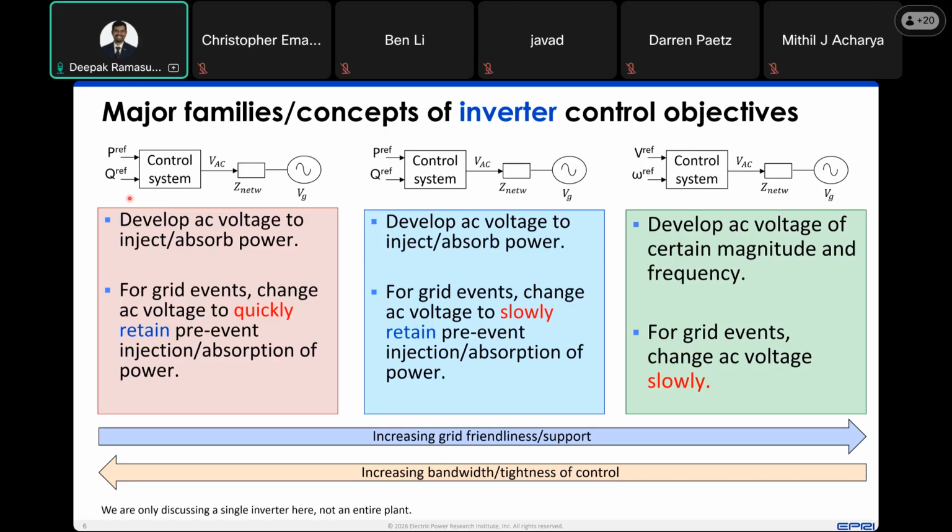If you have a power flow solution where all of the buses, or a majority of the buses, are PQ buses, and you have a contingency occurring in the system, then it's more than likely that the power flow solution will not converge, because the P and Q injection is kept constant at all of the other buses.